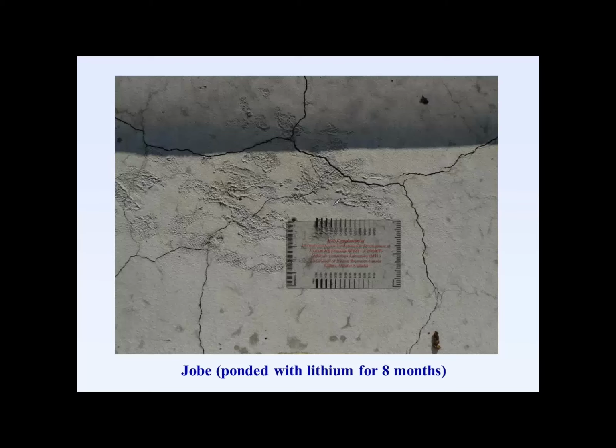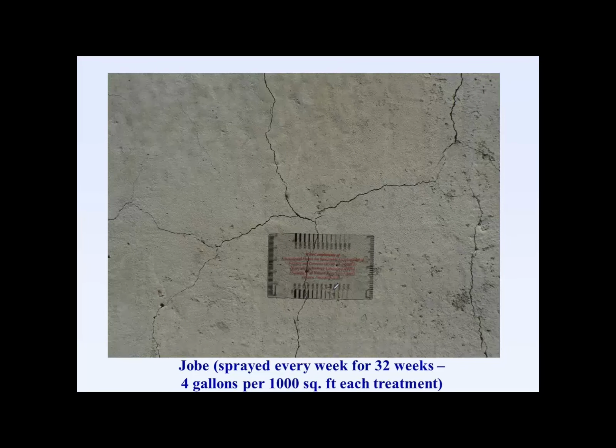In the second block, we constructed a dike on top of this block where we continuously ponded lithium nitrate solution for 8 months. Now we know this isn't practical in the field, but we at least wanted to see, best case scenario, what if we could get the lithium in, and what the effects would be on the expansion. This here shows that the cracking actually was about the same or even worse when we had the continuous ponding for 8 months.